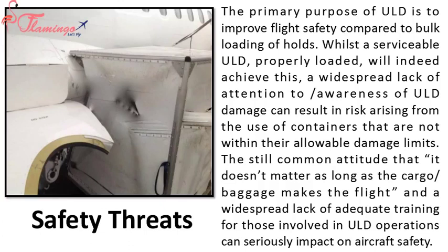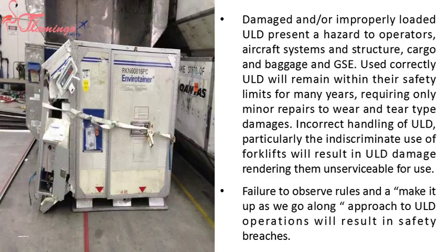The still common attitude that it doesn't matter as long as the cargo/baggage makes the flight, and a widespread lack of adequate training for those involved in ULD operations, can seriously impact aircraft safety. Damaged and/or improperly loaded ULD present a hazard to operators, aircraft systems and structure, cargo and baggage, and GSE.